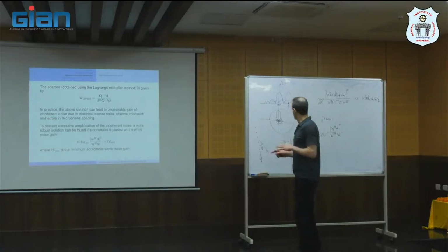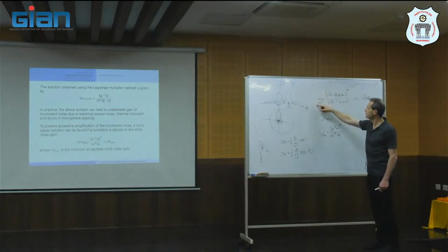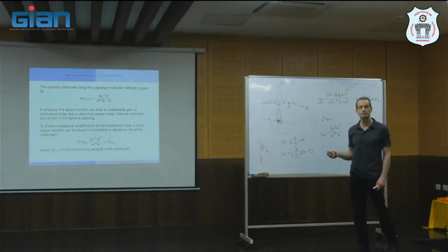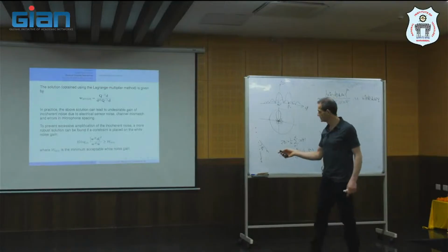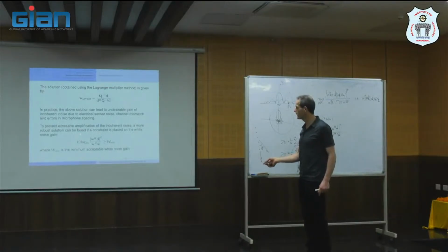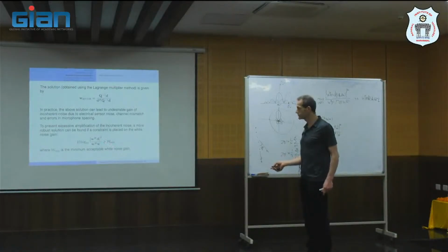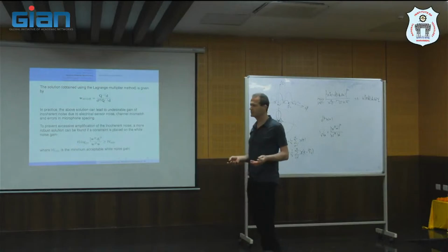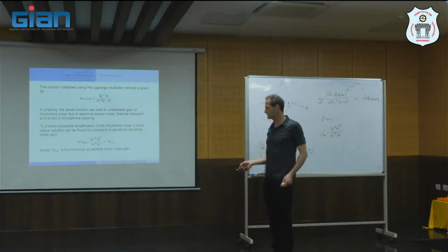So it's not enough to formulate the problem like this, maximum directivity or minimum variance distortionless response beamformer. Usually, in practical cases, you need to add another constraint, that the white noise gain is larger than a certain threshold. Sometimes this threshold is independent of the frequency. Sometimes you may want it to depend on the frequency, but usually you can put a threshold that is independent of the frequency.